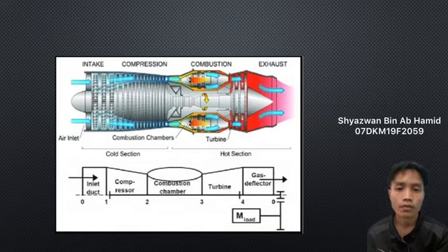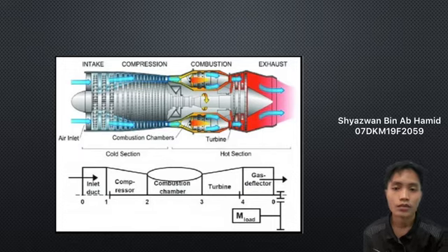The cylinder houses many important components of the internal combustion engine, including the injector nozzle, piston, spark plug, combustion chamber, and others. It provides a confined space for the combustion of the air and fuel mixture. It houses the inlet and outlet valves for incoming and outgoing mixture. It houses and guides the piston. It helps in proper combustion by proper geometry. It withstands the high temperature of combustion. It prevents the spill out of the exhaust of combustion.